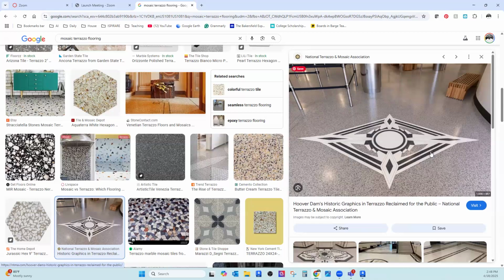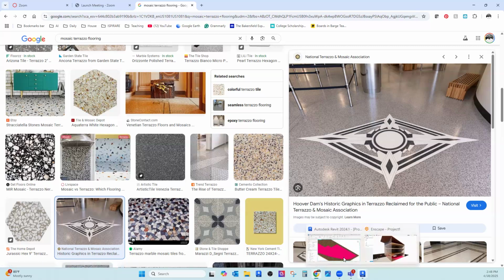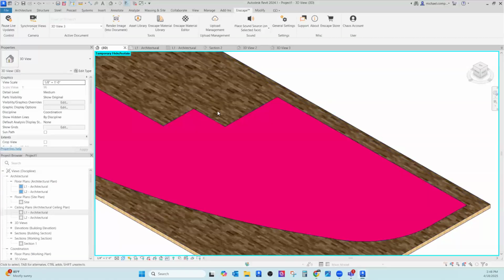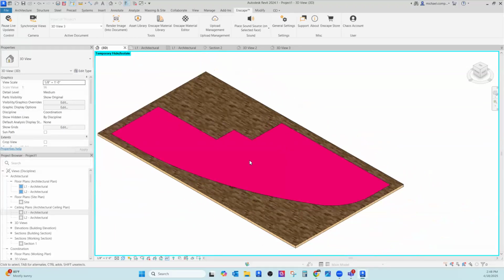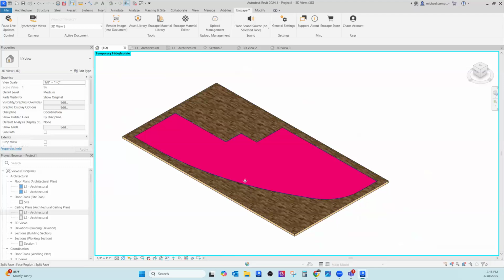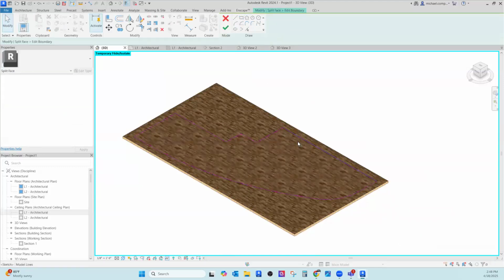The easy way gets complicated because the split face tool doesn't work when you're touching lines. So you would have to offset the split face by 1/16 of an inch to make two different faces. I'm going to show you what I'm talking about. Then you would do the hard way, truthfully. So here we are again, split face, but instead of that, and I can edit this, it doesn't have to look like that.